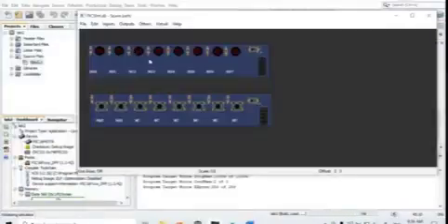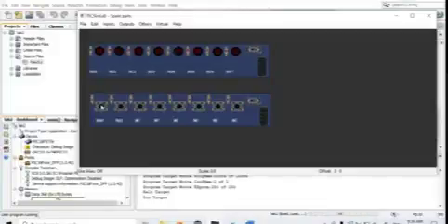You see nothing is happening. Why? Because we are not pressing any button yet. In order for the LED to turn on, the button here must be pressed. So we start with RB0. RC2 will turn on here. And then to turn off, we press RB1. If you press multiple times, nothing happens.